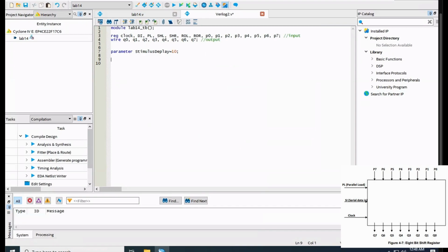But an easier way to do this is to use DUT. For test benches, the HDL code, which is hardware design language code, is written to test another module. So that's what we're doing right here. That's what the test bench is for. The device under test is what DUT means. We can also say unit under test. So those are the two different meanings, device under test and unit under test.